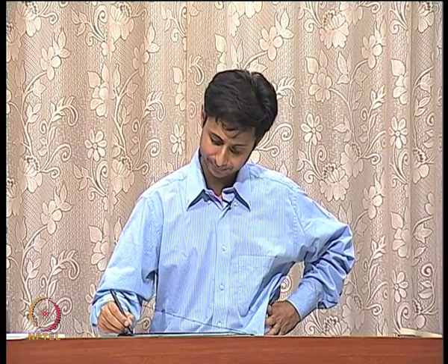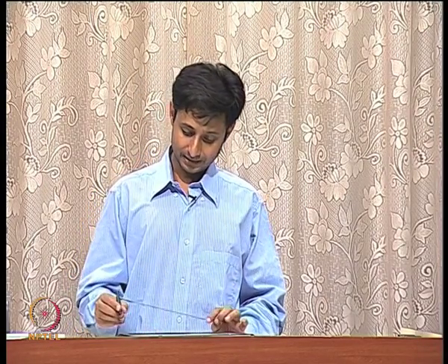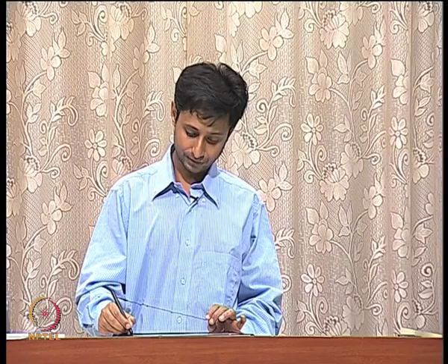This phenomenon is called Miller effect, right. So, it is as if C gate to drain is being multiplied by the gain of the device. I have a gain of 10 for my device, and the effective capacitance now for C gate to drain is something like 10 times 50 femtofarads. So, 500 femtofarads instead of 50. Now, that was bad news, that is really bad news, and that is basically what causes problems.